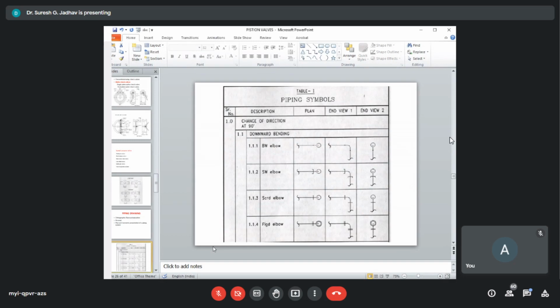In complex systems, especially within unit or plant buildings where orthographic views do not illustrate the details of design, pictorial views in isometric presentation are drawn for clarity. Especially printed isometric sheets are available with lines drawn vertically and at 30 degrees clockwise and 30 degrees counterclockwise respectively from the horizontal axis of the paper, by the use of which 3D representation of the pipeline can be prepared.